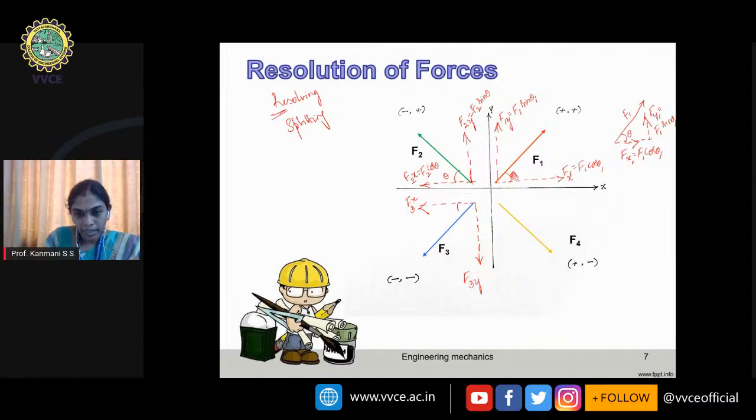Again, if the angle is with respect to horizontal, then adjacent to the angle, we are going to get f3 cos theta, and opposite to the angle, that is this side, which is very similar to this, that means having the same scale, I can write it here. So f3y is directly equal to f3 sine theta. Or else put this type of triangle, you'll get the same answers.